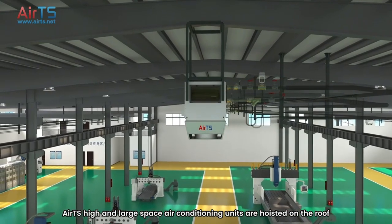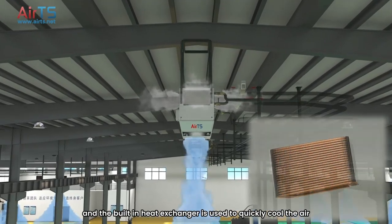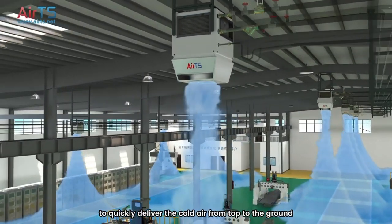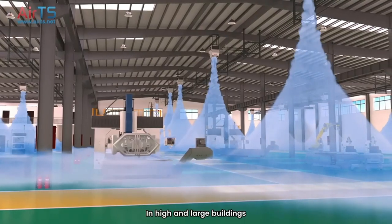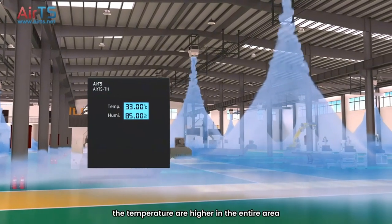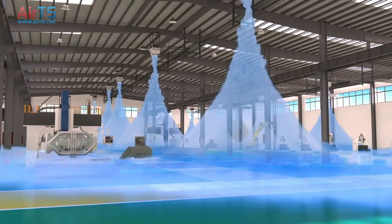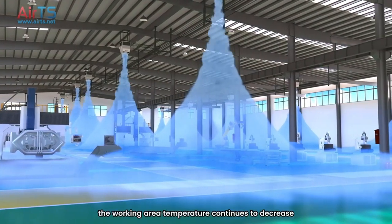AirTS high and large space air conditioning units are hoisted on the roof, and the built-in heat exchanger is used to quickly cool the air. Then, use efficient air distribution device swirl diffuser to quickly deliver the cold air from top to the ground, evenly distributing throughout the space. In high and large buildings, when the device is initially started, the temperature is higher in the entire area and the device works at the maximum cooling output state. As cold air is continuously delivered to the ground, the working area temperature continues to decrease.